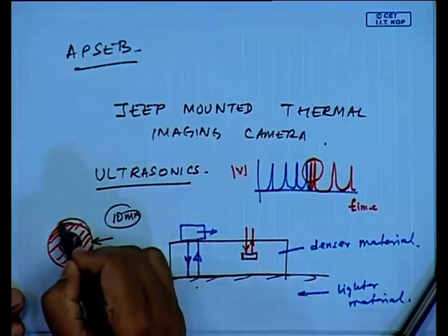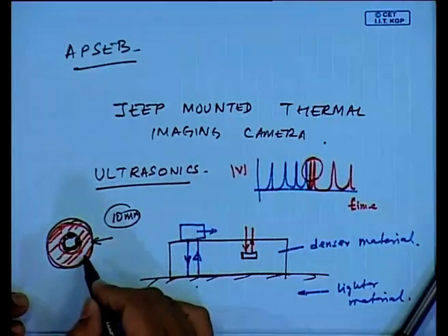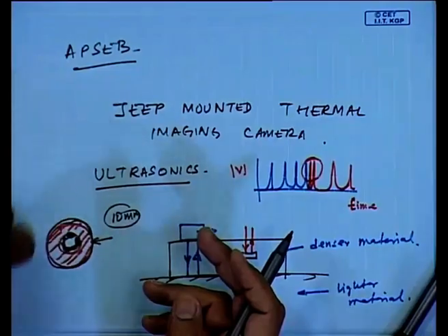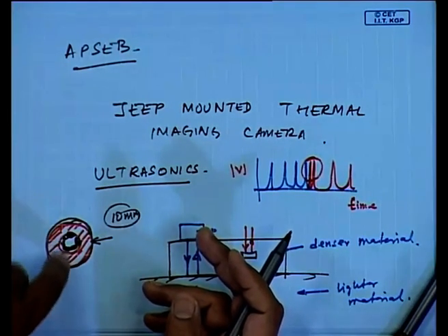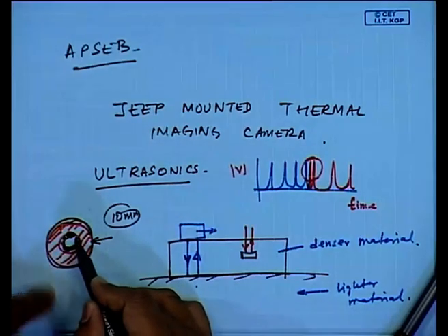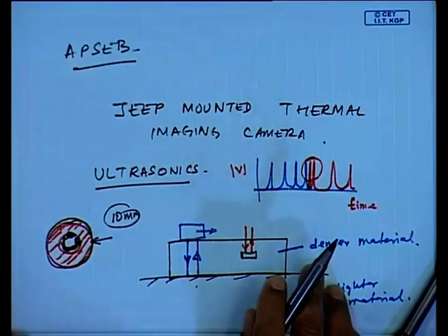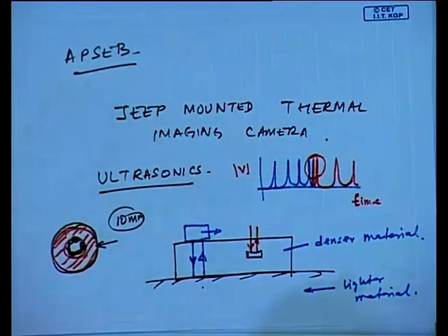And if you rove an ultrasonic transducer all around the circumference of this tube, you will know what is happening internally, which is not visible, and which possibly vibration monitoring cannot measure. I can know if there is any formation or deposits in the inner wall of the tube. People of course use radiography also, X-rays, which is another way of doing it. So, there are many NDT techniques like ultrasonics, acoustic emission, radiography, etc.